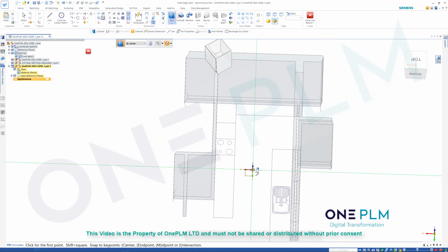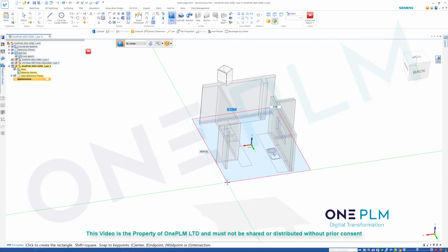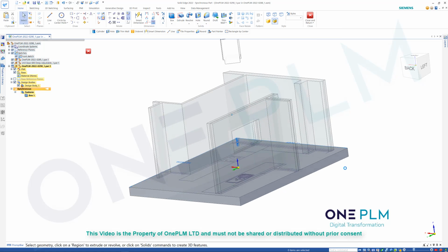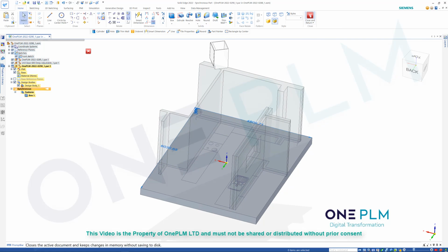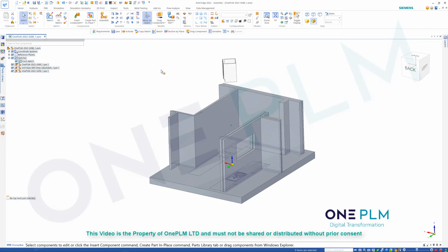So this little box tool up here allows me to choose on there. So I want my box to be on that plane. Do the F3, the same as what we did before. So I want to make the floor about that size. And I'm going to go down. Let's just go down 300 mil on there to represent hardcore concrete base, etc. And then we can close and return when we've got that looking nicely.